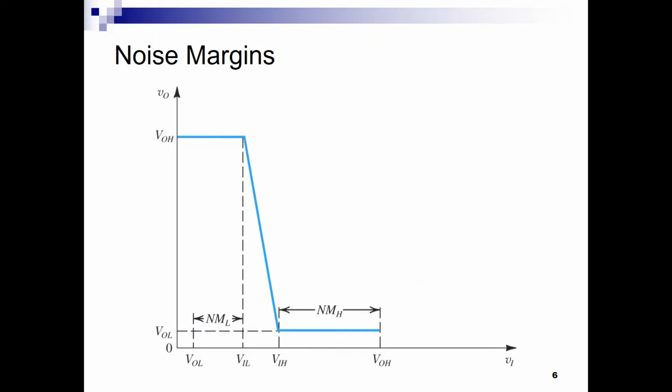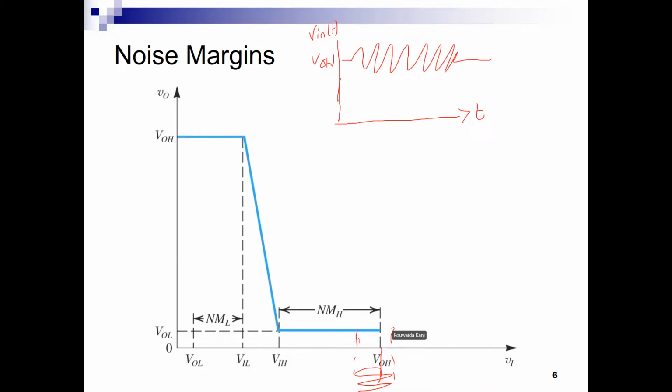Okay. So let us assume that I get an input pulse that is constant, Vn of t here constant, right? As a function of t. Now let me assume that my input has noise. Noise came on the system, and the input became noisy, centered around VOH. Okay, but it still keeps me at this level. Here is the input. Okay, what is the corresponding output? Of course, if I increase it, I won't be affected. What is the corresponding output? It stays VOL. Right. So Vo of t will stay VOL.